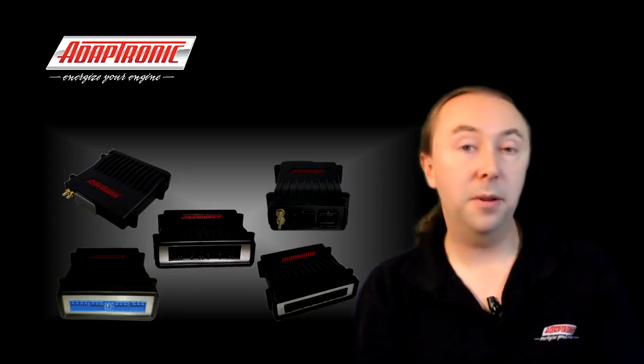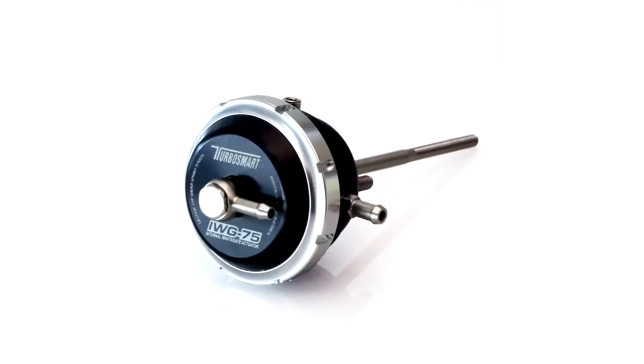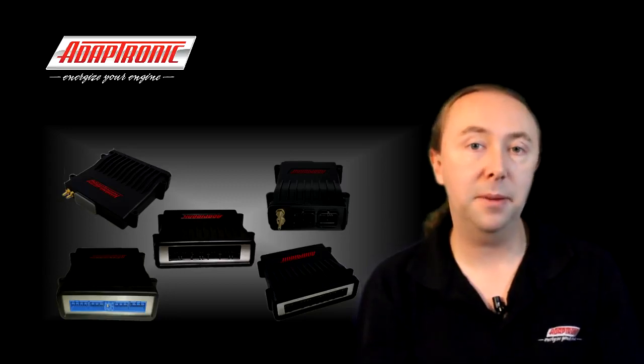Now, as well as the single port IWG that I mentioned before, TurboSmart also have a dual port version of the IWG, where both sides of the diaphragm have got ports on them, so you can control the pressure to each side individually. With the single port, one of them is always open to the atmosphere, so the other side is the one that you have to get to your target spring pressure.